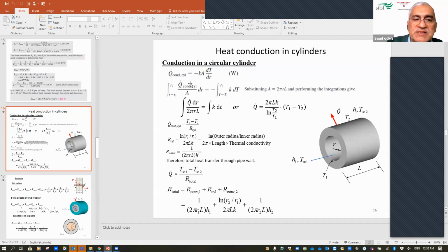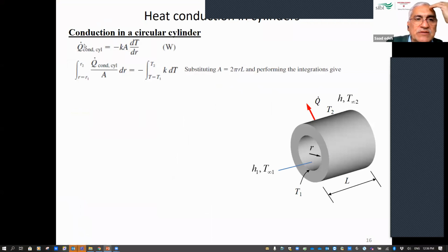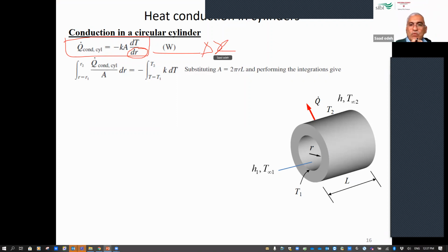the same thing. We'll apply the same rule, which is the Fourier law of heat transfer by conduction. And this is the major law that we use every time. Remember this. But before, rather than have dr, we used to have dx, remember? Thickness. Here, the thickness is actually the thickness of the wall. So rather than saying dx, we have dr. So this is the wall thickness.